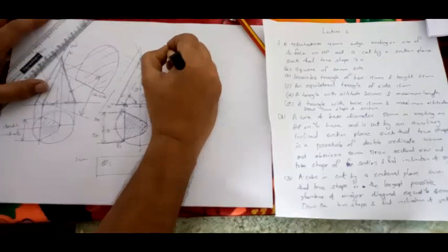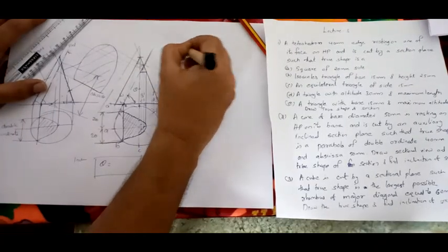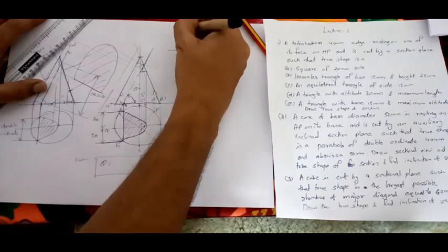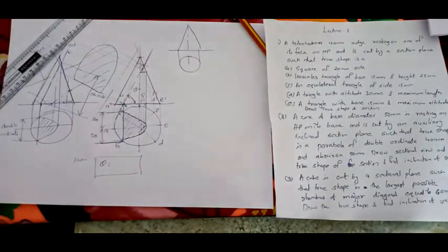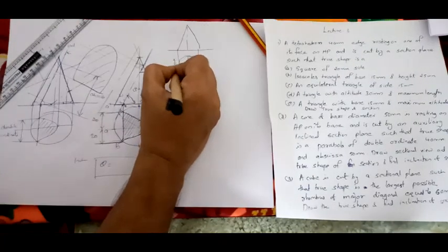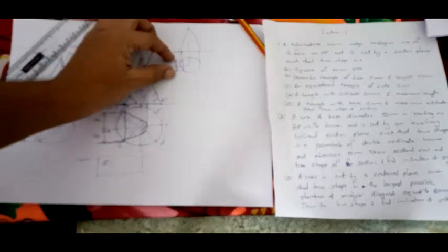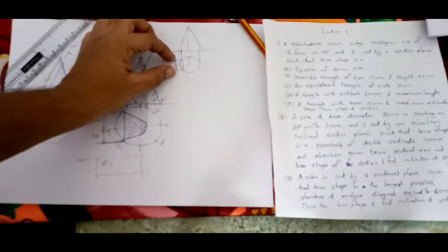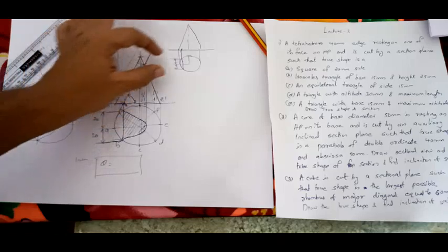Very simple. If you have a cone, draw the complete cone. If they have given the height, you can complete the cone. Now, if they have given the double ordinate, take 20 mm towards both the ends of the 40 mm, cut the points, and you have obtained it like this. You can do the same thing here.